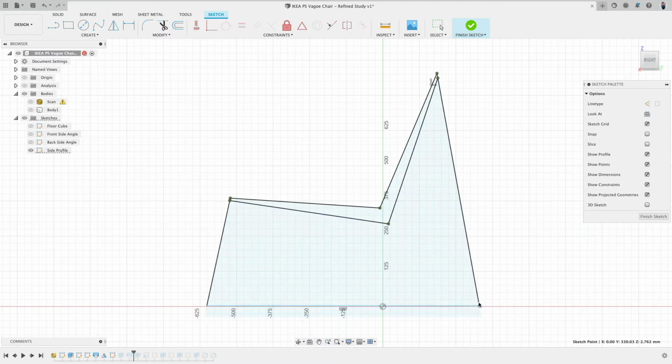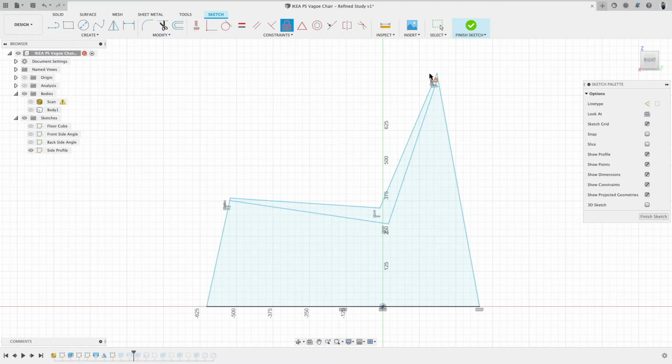Okay. So now I can move this point up. It will move this point up. This stays horizontal. So that means U, horizontal to U. There we are. This way, none of these lines would move. I can press escape, and if I want these points, I can alt select again and unlock.